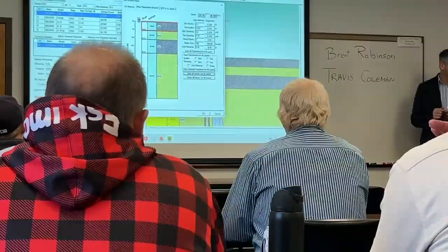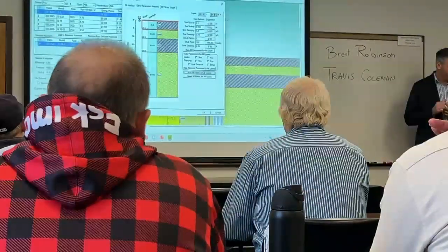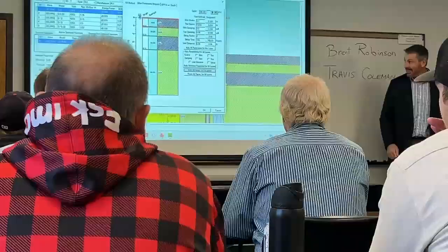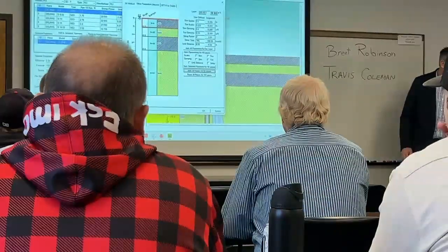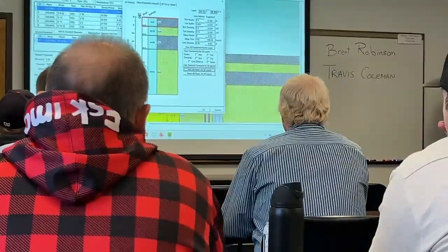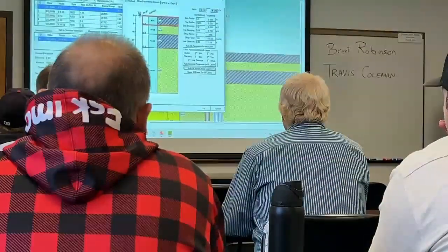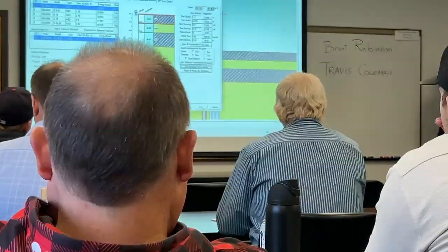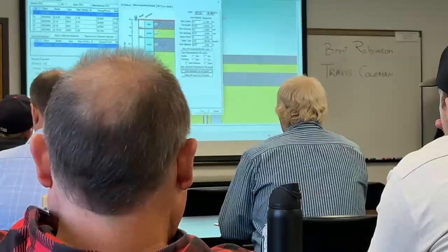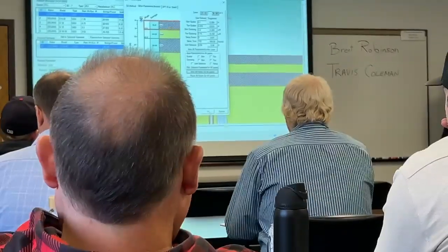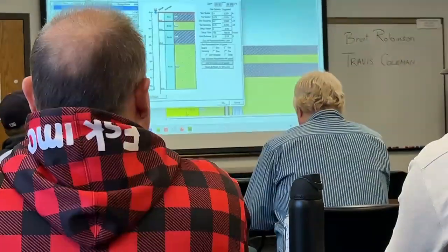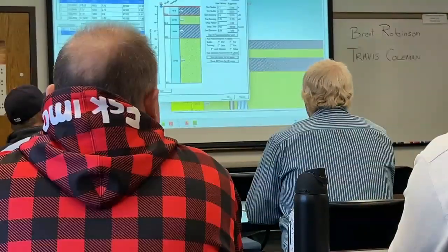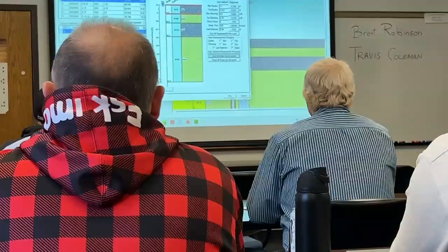So it's going to say your clay layers have a damping of 0.2 seconds per foot. Your granular soil has a damping of 0.05 seconds per foot. So if I'm doing that static analysis and this doesn't mean a lot to me, I'm just going to input those recommended values. The only time this could really get you in trouble is if you have rock or hardpan, something like a very dense, stiff clay where you don't know those parameters, and you're going to have great effects on your results based on what you assume.